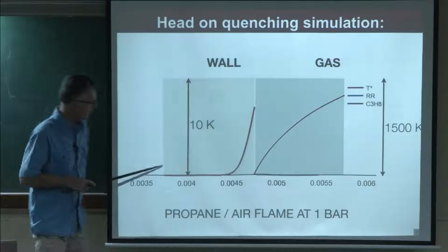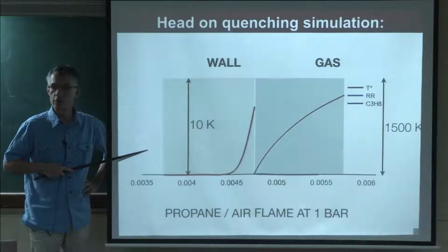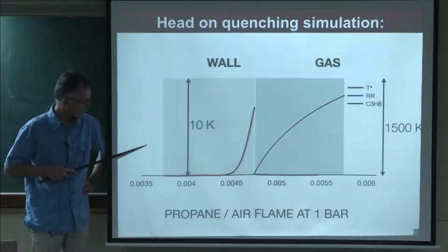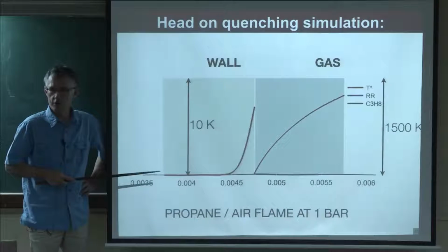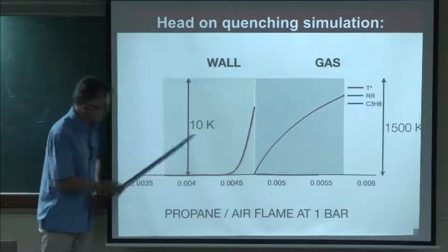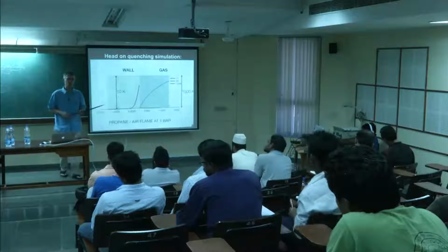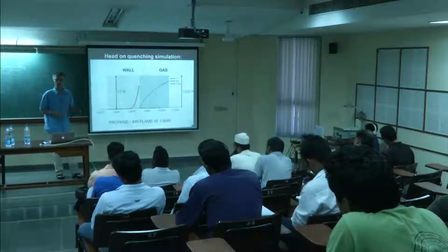No, if it's realistic, it's still going to be isothermal, because what you have here is cooling water. And then if you have water, the temperature will be imposed at the cooling water temperature. And so if you repeat this interaction many times, then you will end up with a profile which is almost straight. Because on average, it will reach a steady state.